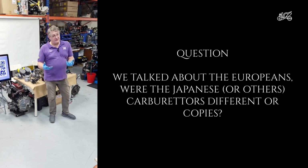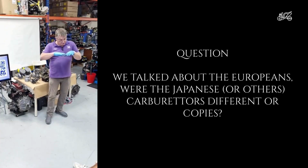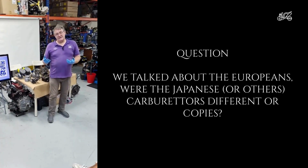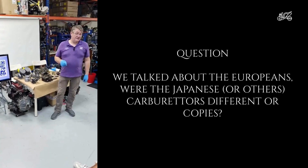The reason for Strombergs is there was enough demand for carburetors that Stromberg could copy the SU principle without conflicting with their IP. So a Stromberg has got a piston going up and down, but it's got a rubber diaphragm and some other bits and bobs in it. So it's a reverse engineered copy of an SU.